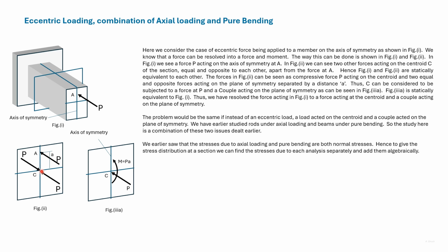These are two equal and opposite forces which are parallel to P and have the same magnitude P, acting on the centroid. The loading here and the loading shown in figure 1 can be considered to be statically equivalent, since all we have done in figure 2 is add two equal and opposite forces.